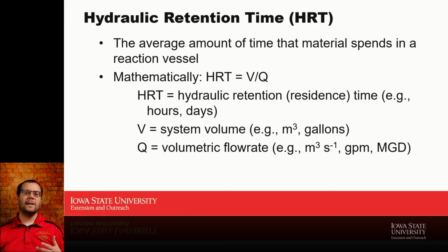And generally we'll size a hydraulic retention time, a solids retention time, for most practical digesters in the agricultural spectrum. Our hydraulic retention time or solids retention time is the same. So I'm going to just talk about hydraulic retention time. If you have really unique situations, we can come up with more sophisticated designs that separate those two, because we really want a big solids retention time, and it'd be okay to have a shorter hydraulic retention time. But that adds a lot of sophistication, oftentimes cost, and challenges to management. But that hydraulic retention time tells us how much stuff we really need to store, right?